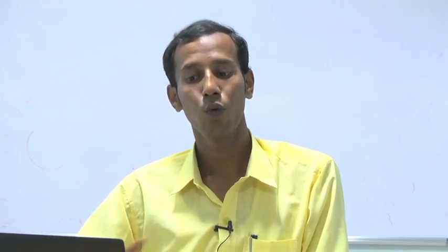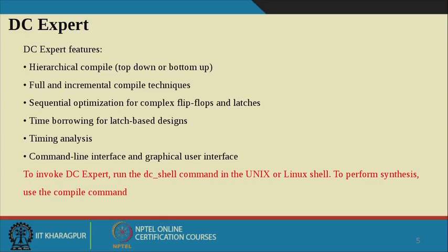Whenever we use this Design Compiler tool, it does not run in Windows; it runs either in Unix or in a Linux shell platform. In the Linux shell, we have to type the dc_shell command to open up the GUI for Design Compiler.